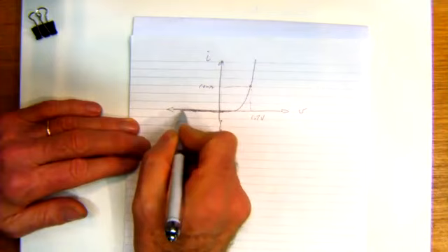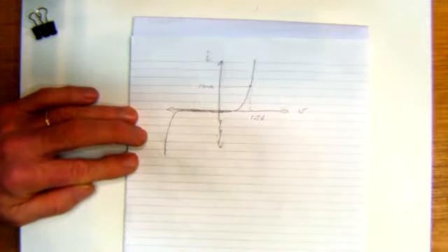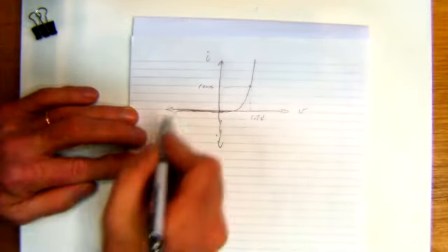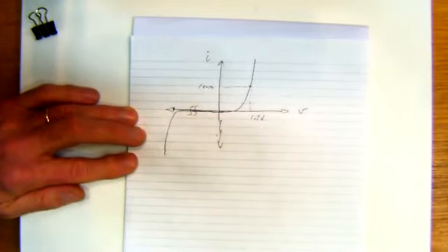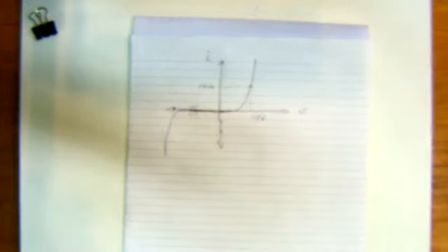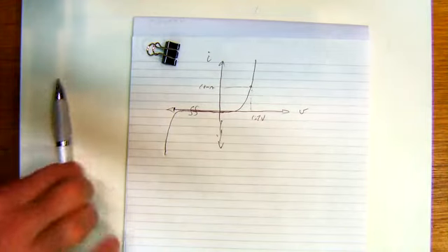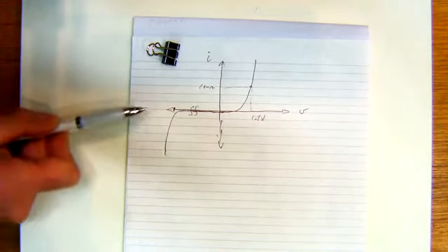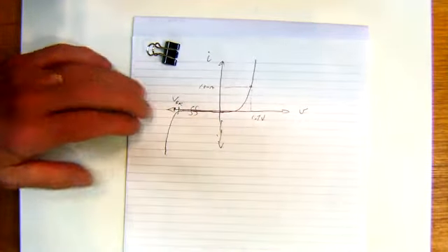In the reverse direction, a typical diode has a breakdown voltage in the negative domain after a specific point, and that depends on the way the diode's manufactured. At a certain point, there will be a breakdown voltage here, and with LEDs, it's usually around 5 volts or so.